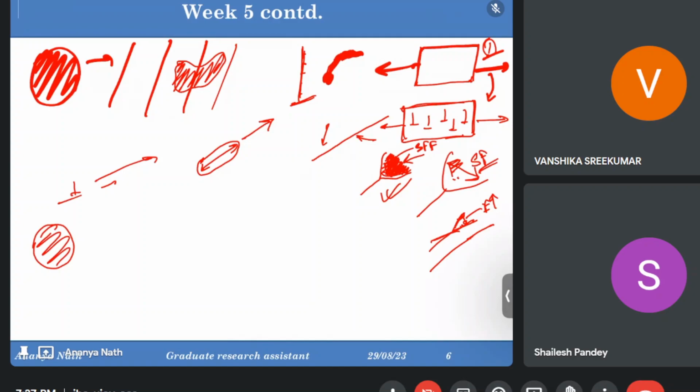But for cold working, you are stretching the material and you are doing the strain hardening. But again, to get back the ductility, you cannot stretch back, right? So for non-heat treatable alloys, it's a problem to get back the ductility. You have to go for other things to get back the ductility. But for heat treatable alloys, it's fine.